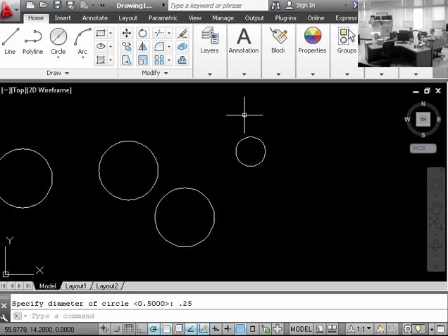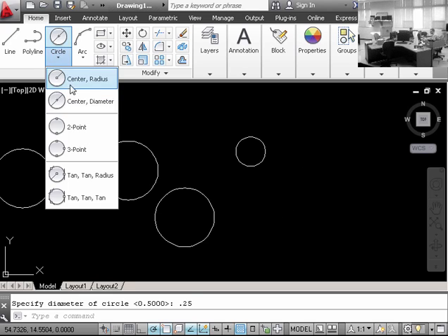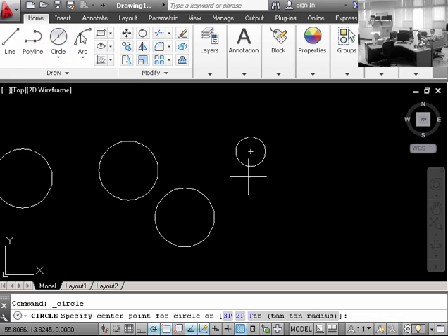But that's a little bit of a way to speed it up. If you just want to do it one shot, come up here, hit the pull down, hit diameter, and then keep clicking on it time and time again. There are more ways to speed stuff up, but we'll get to that a little bit later on. Other questions with that in mind?